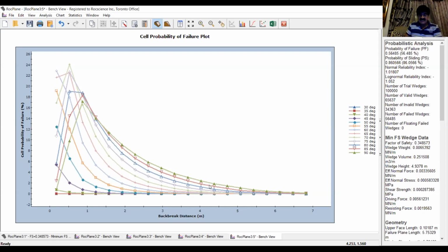And you have looked at both the cases. From the previous managed approach, we looked at 49 degree, and when we looked at the bench width, we reduced it to 48 degree. So we know that a 7 meter wide bench and 48 degree is what we can do for managed. If you apply the same rule, let's look at 48 degree. Where is 48 degrees in this? 50 is this one. So 48 is somewhere here, close to 50, which quite matches. You might live with this. So anyway, this is how it can help you. But this is what we are looking at the bench level.